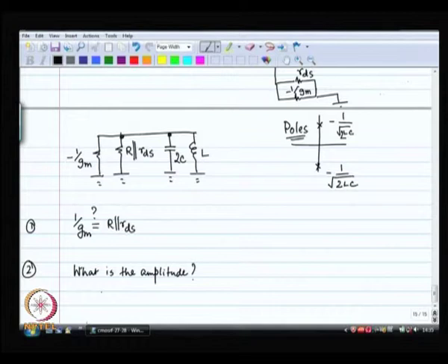Anything in my circuit that is deciding what the amplitude of my oscillations are going to be. We have done some small signal analysis. We have figured out the small signal input resistance of the cross coupled pair that happens to be negative, right. Is the amplitude also going to be small? Because if the amplitude is small, then it is bad news. What is this amplitude going to be? That is the second question.